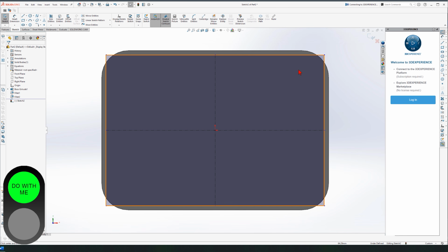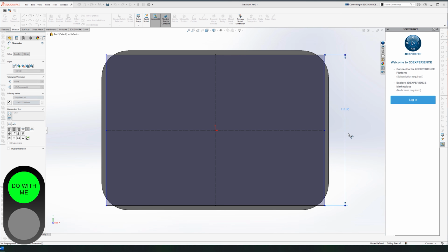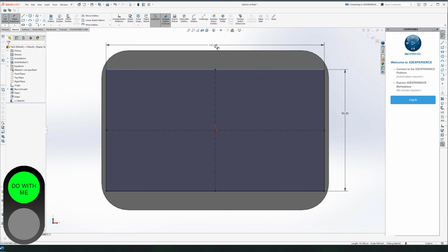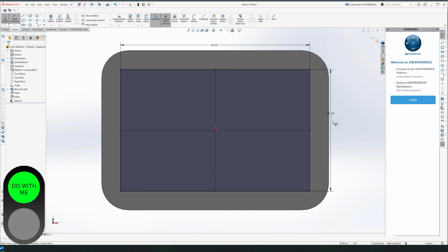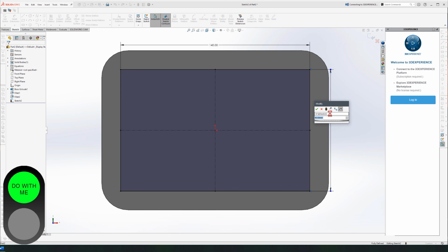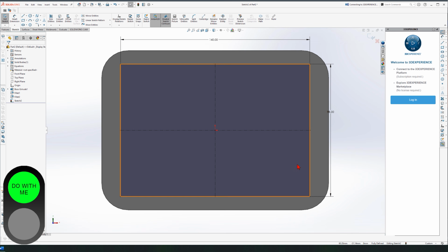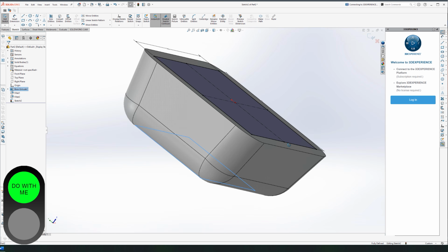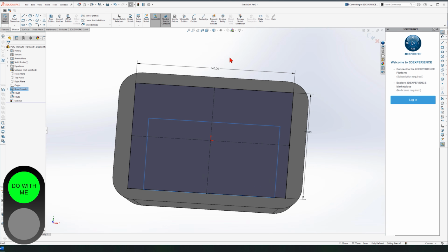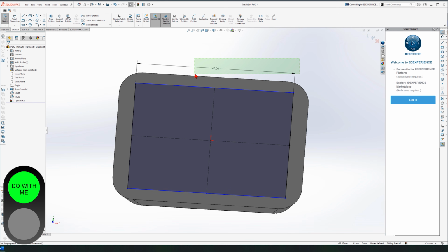We had it 100 by 150, so let's do that smaller this time. Let's go by 90 and 140. But doing so, we are giving it a wall thickness of 5, which is too much. So if we want to do wall thickness of 1, instead of 90, we have to do 98. And sorry, it's my bad, because that dimension was for the smaller rectangle, not the outward drafted. So these values are not valid. So I just select it, press delete, select this dimension, press delete.